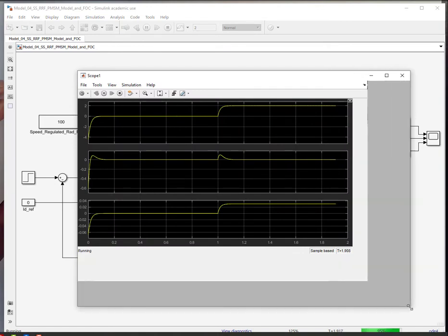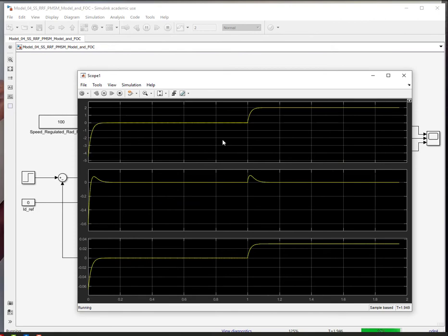All right, so the first is your Q-axis response. So I'm injecting a very small current. So initially set your starting current to be about 0.01, and then I'm injecting a step input of 2 amps. The reference is being changed to 2 amps at t equals 1 second, and we can see that the controller is following that.